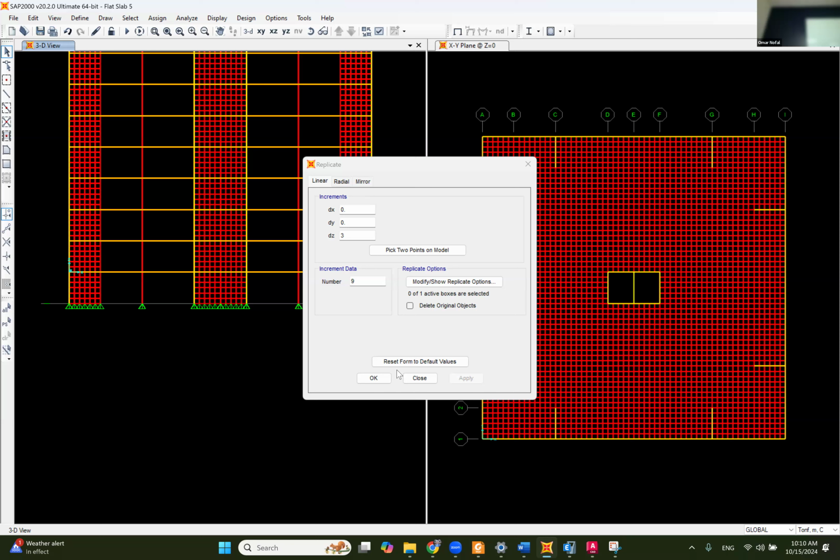And usually if we have a tall building like 60 stories or something, we design the base floor, and this is the biggest column that we're going to have. And then as you go up, the column cross section needs to go down. But the thing is, you have to design 60 times these columns because you have 60 stories. But we don't do this. Maybe every 5 stories, get the moments, the forces, and then design, or every 10 stories. Depends on how much. But sometimes designing columns is going to save you a lot of money. Okay. Thank you. All right.